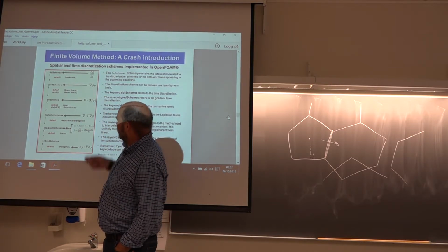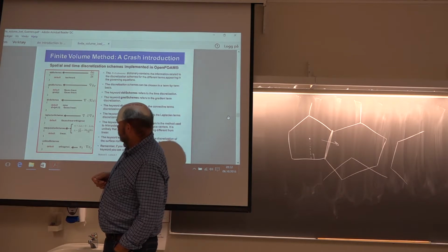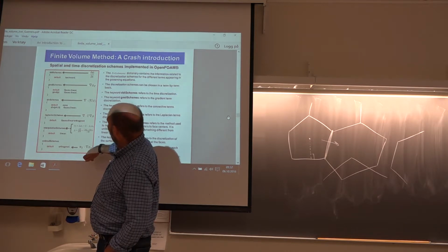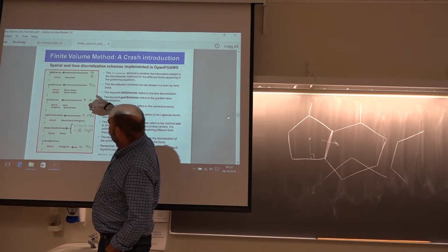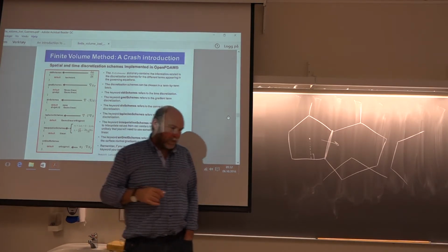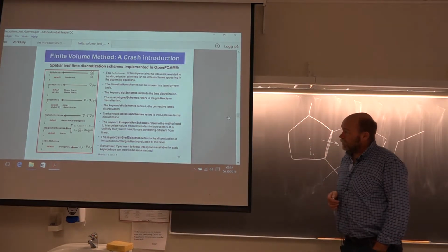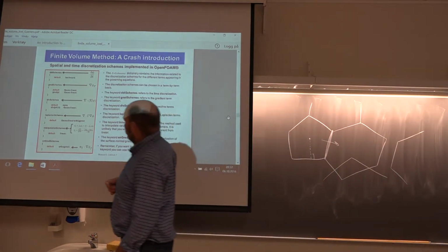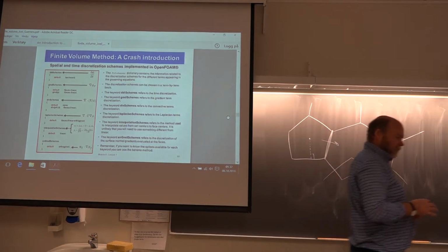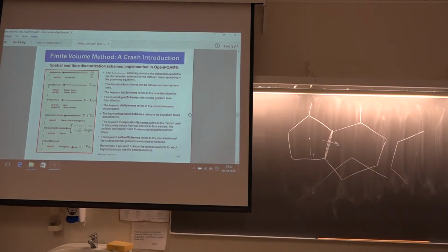No problem with these. So the question is this one, divergence of the transport there. How this one should be handled. So here I've chosen Gauss linear. That's not recommended, I would say, because then you are talking about a central scheme. So it will be very, very unstable.